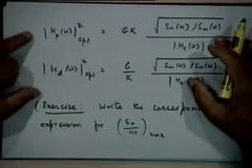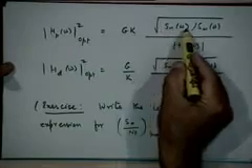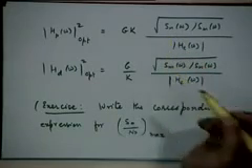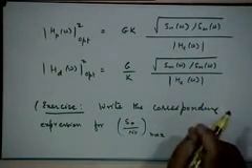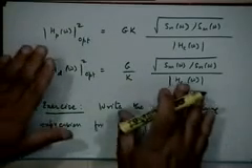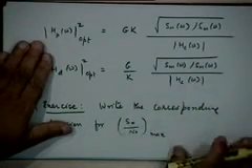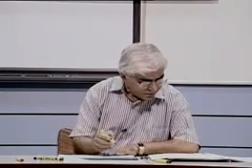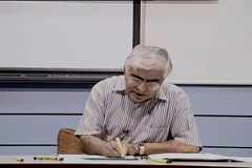So before the pre-emphasis filter, I have no idea about the noise which is going to be added afterwards. So you have to have some idea. If you want to do the optimum design, you have to have some idea. For example, even the knowledge that it is white Gaussian noise is helpful, right? If it is white Gaussian noise, you know what it is, and if it is not Gaussian, if you know what it is, you can optimize further, right? You have to have some idea in order to use this theory, right? And there are ways of finding it out. So the physical significance I'll just summarize and then we'll move on.